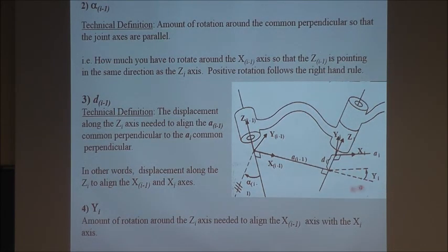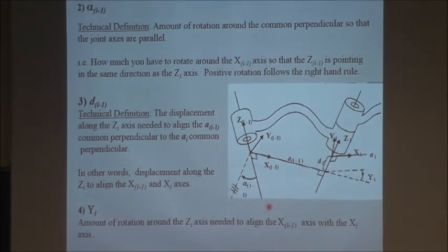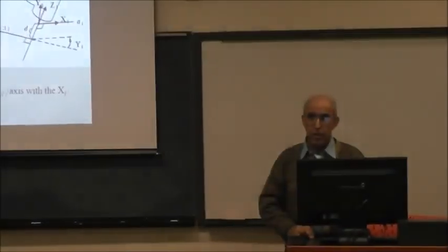You rotate along the z_i axis so that x_{i-1} is aligned with x_i. x_{i-1} is this, look at the continuation of the dotted line. It rotates this much. Remember, when you go from coordinate to coordinate, you saw that in those two-dimensional examples. In order to go in a 2D area, you need both translation and rotation.